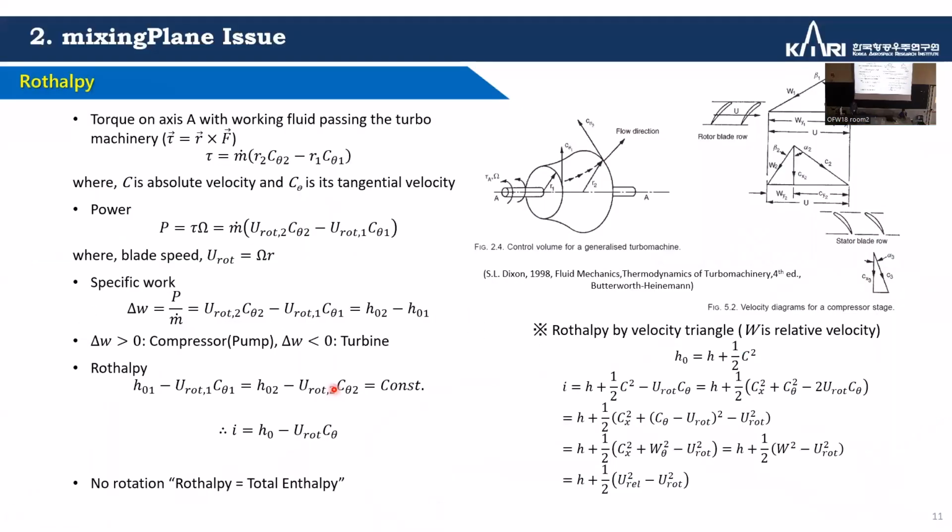Before starting the mixing plane issue, we need to review rothalpy. This is how you can derive the rothalpy definition. The important thing is that rothalpy is conserved from the inlet to the outlet, and it is like the total enthalpy.